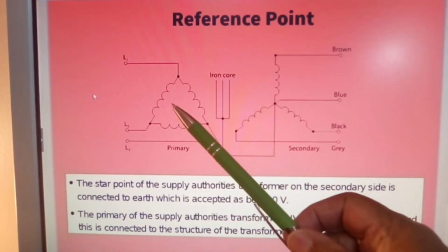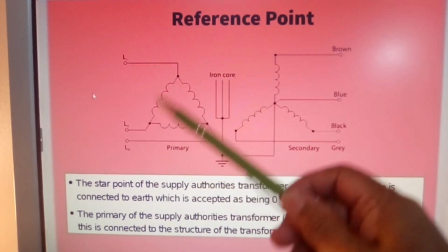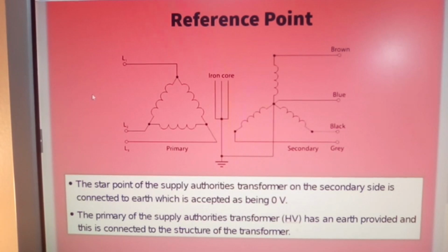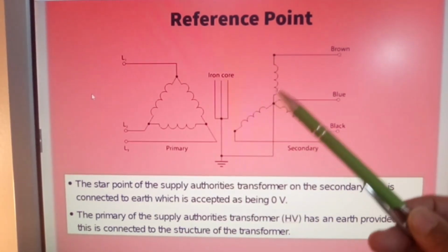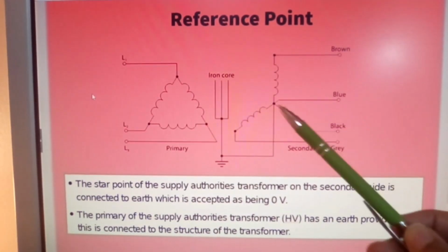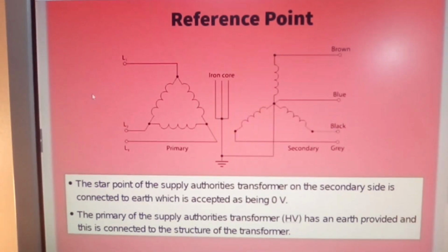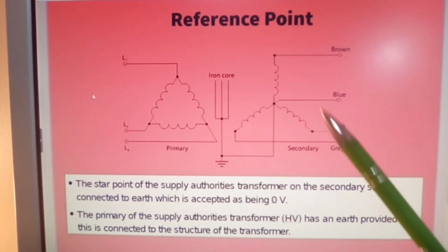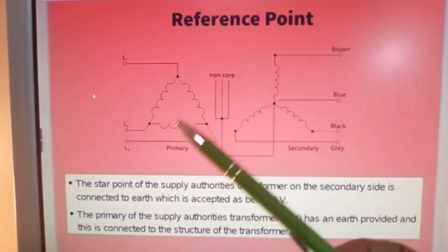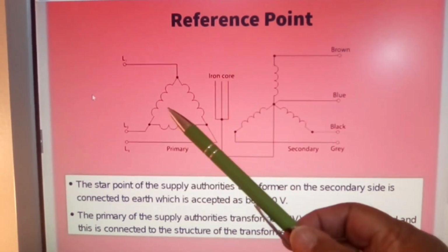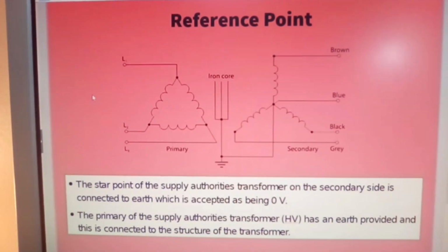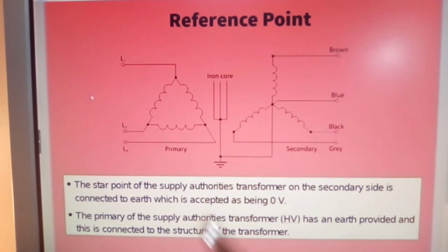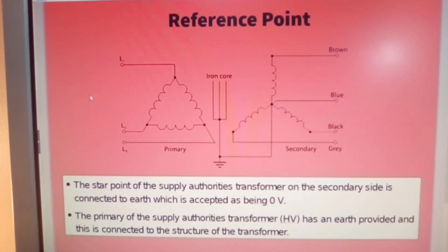Now this is your delta connection. You'll find that there's no star point on your delta part of the transformer. But star connection, you have a center point, you have a tapping that brings you down to Earth. Okay? So you can take off various voltages in the star connection than you can in the delta. Delta allows you to have a great deal of current there, thereby allowing your transformer on the star side to be able to have power to draw on.